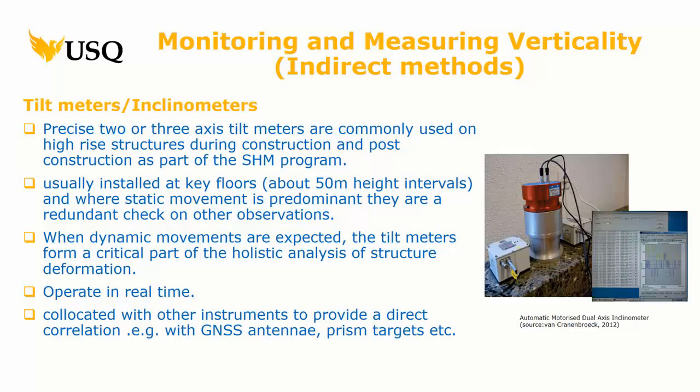As a senior surveyor, you might be asked to set up a data collection center, integrating that data. Now, where that's important is you're talking about, in a lot of cases, real-time least squares adjustments on the fly, right? A mix of data sets. Now, you're probably trying to get software to do that, but it's very important you understand what's going on behind the software so that you understand what you're likely to get out of it, right?